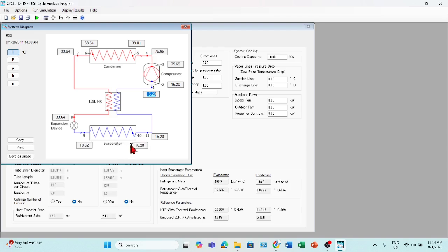These are the evaporator outlet temperature after superheat, and then this is the liquid line, suction line, heat exchanger, which we are not using in this cycle, and then the compressor inlet, compressor suction line, then compressor discharge line, and then the inlet of the condenser, outlet of the condenser subcooling, and then so on, expansion valve inlet and expansion valve outlet. You can also change and see, instead of temperature, the pressure values, the density values, the enthalpy values, or the entropy values, whichever you like.